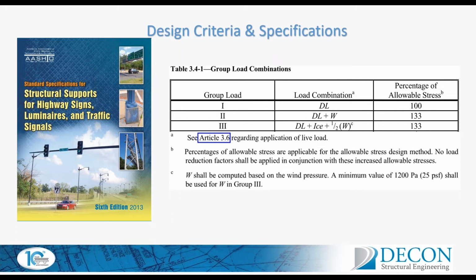Also, as mentioned previously, the live load is not considered here because it depends on its applicability. Usually, live load is 500 pounds, and only the members of walkways and service platforms are designed for the live load, nothing else. That's what the code says.